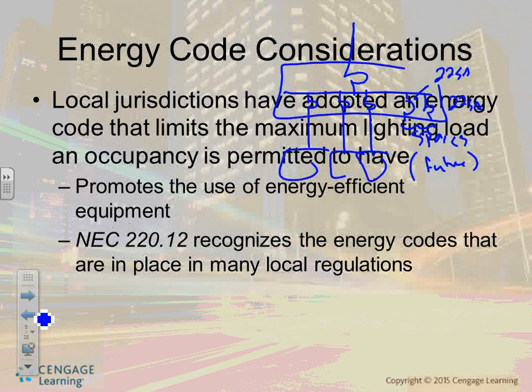There's a difference between spare and space. If I say spares, these circuit breakers exist. If I say space, what do you guys think? It means leave a slot for them. A space is a slot, no circuit breaker in it. Leave a slot equivalent to 225 amp to fit a 225 amp.